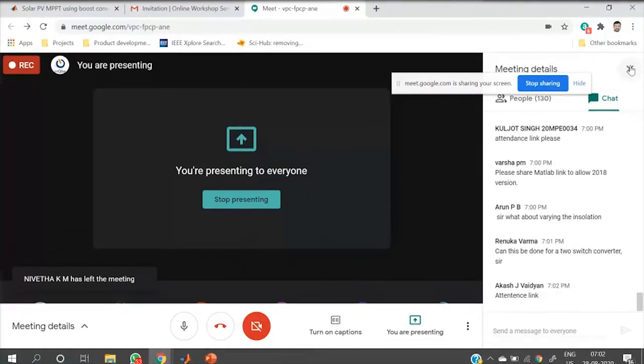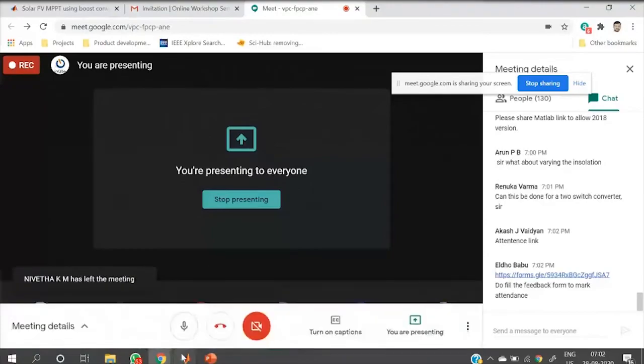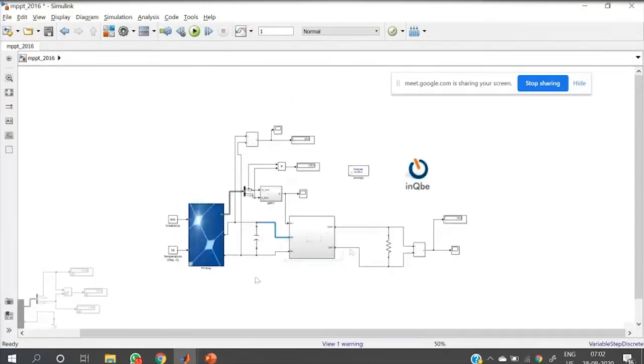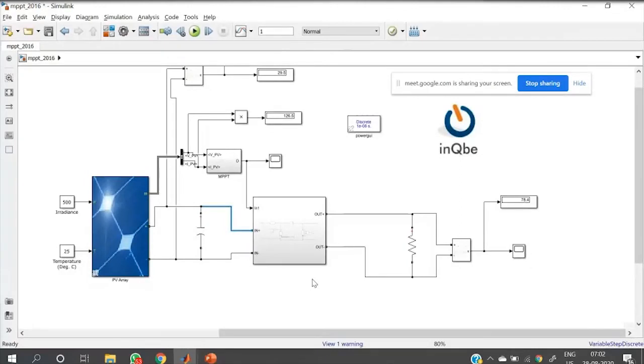There's another method that's known as indirect MPPT. In that case, we'll apply a closed loop control to control the input voltage. We can apply a similar closed loop control to what we applied yesterday, but feedback will be from the PV side. In that case, we will not vary the duty cycle directly; we will vary the voltage command. Yesterday we gave such commands for voltage, like 24 or 22. That command will be varied by the MPPT controller. That means the MPPT controller will generate voltage instead of duty cycle.